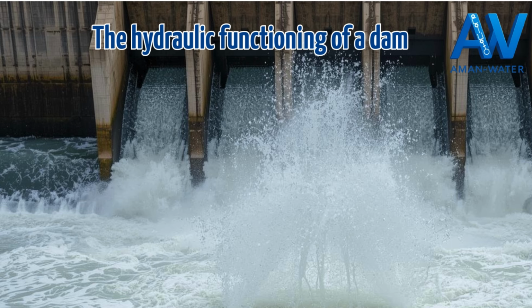The water leaving the dam can reach considerable speed. Without energy dissipation devices, it would cause massive erosion in the riverbed. This is why dams are often equipped with stilling basins or devices that force the water to lose energy before rejoining the river downstream. This prevents the river from deepening or destroying its banks.